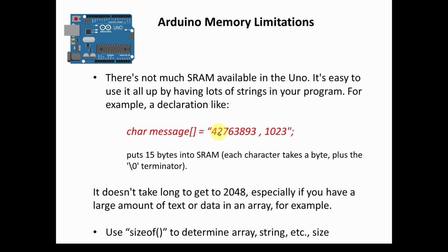And if we have like 100 samples, you're going to multiply this 15 bytes by 100. So the total requirement is going to be about 1,500 bytes for 100 samples. It doesn't take long to get to the 2048. We just said, only 100 samples and you're up to 1,500 bytes. Here's 2048, that is the limit. So we have to worry about running out of SRAM even with our 100 samples.